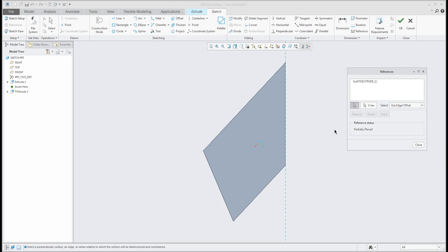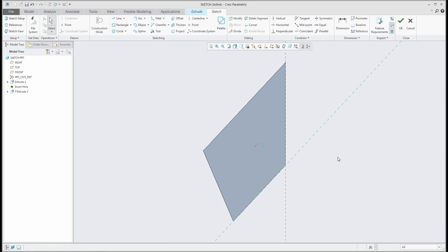Okay, so this is the first orientation. Once you finish the sketch orientation, the system will select some references. You know that in the sketch it is necessary to specify references if you would like to attach lines, arcs, circles, and so on. So right now the system selects this References button and you can add other references. You can add as many references as you need in your sketch. And the question is, what are these references good for? These references you can again use for your orientation.